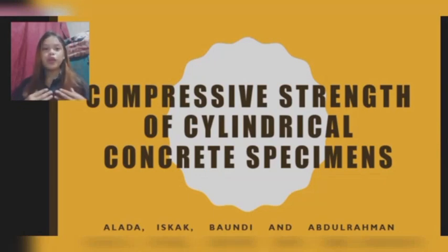We are assigned to tackle the compressive strength of cylindrical concrete specimens. The compressive strength of the specimen is calculated by dividing the maximum load achieved during the test by the cross-sectional area of the specimen. The results of this test method are used as a basis for quality control of concrete.